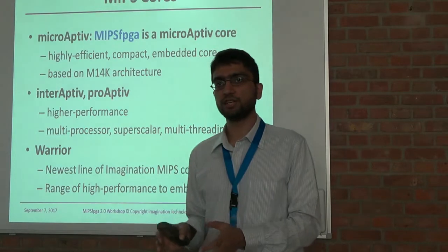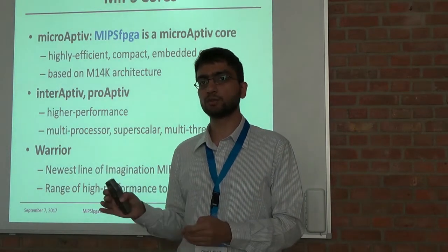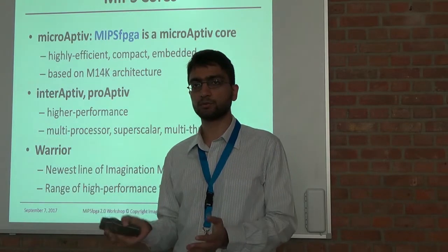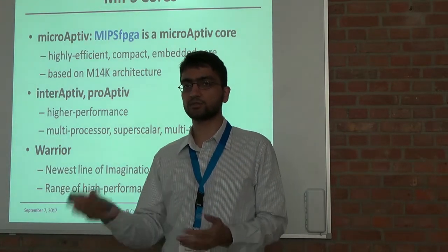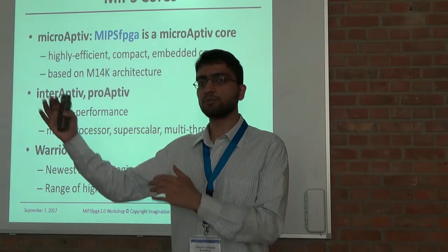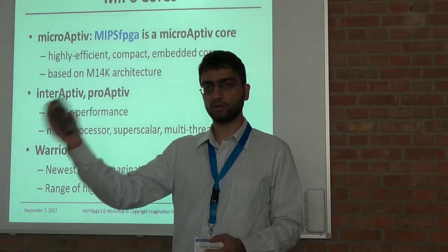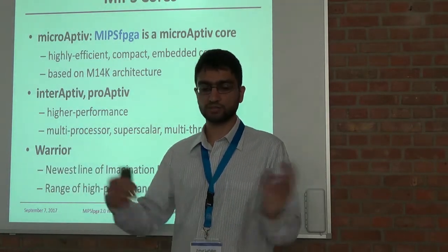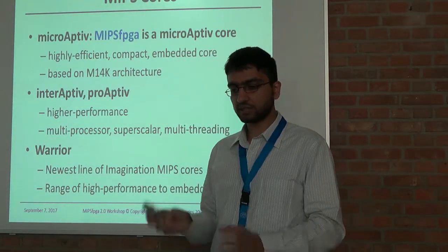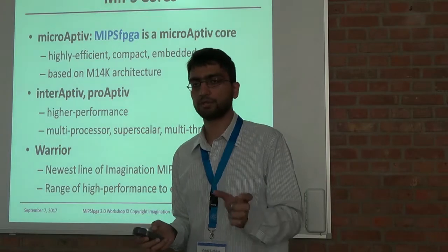Now, MIPSfpga, the core itself, is the M class core, but it can still go up to like 300-400 megahertz clock speed, and it can run Linux. It also has the MMU, so don't be confused that it's a very small microcontroller. It can be configured to be a microcontroller or a microprocessor to run Linux with an MMU, or just a microcontroller. So MIPSfpga itself, the code we give, is the microAptiv.